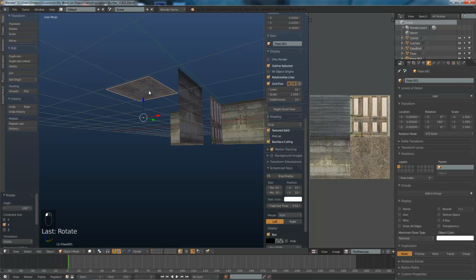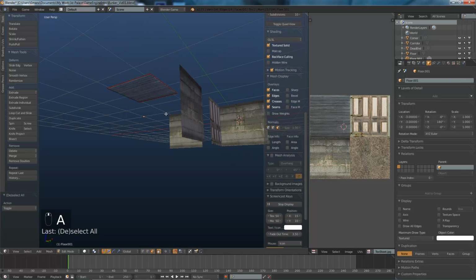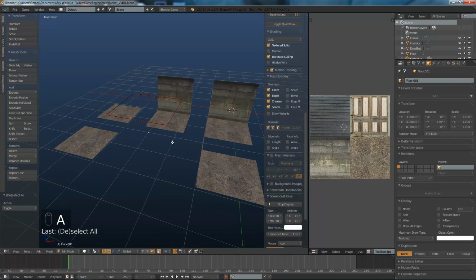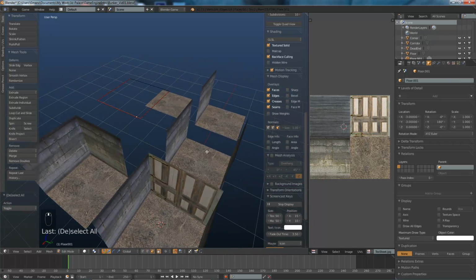And of course the face on that is wrong, that's a floor face, so we need to select it. So I went into tab mode and select that face, and there it is on the floor. So we need to hit A to select all its vertices, hit G and move it up to where the ceiling is, and then just click to deselect. There we go. So we've got a ceiling piece and our floor pieces and all the segments to make our walls with.